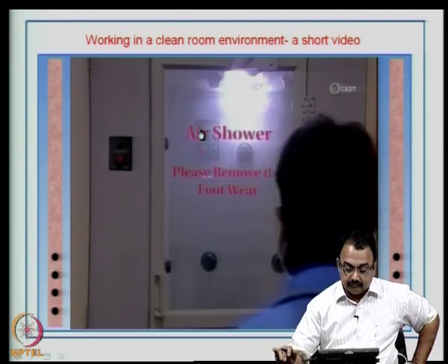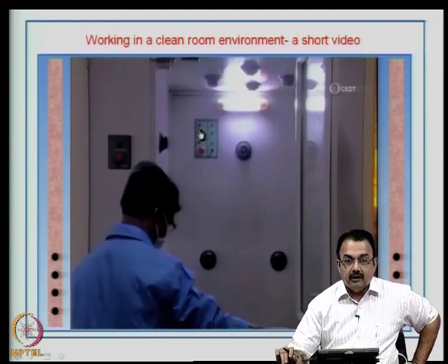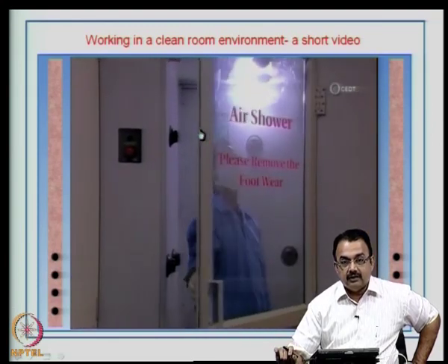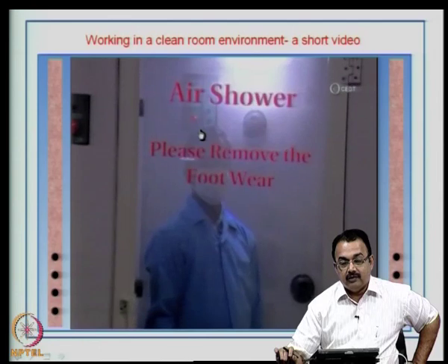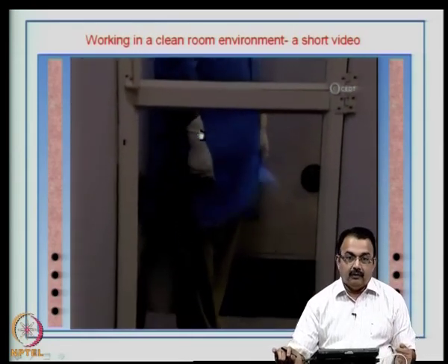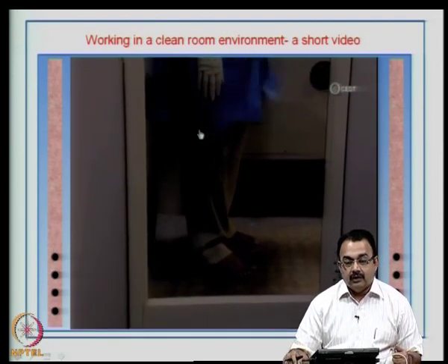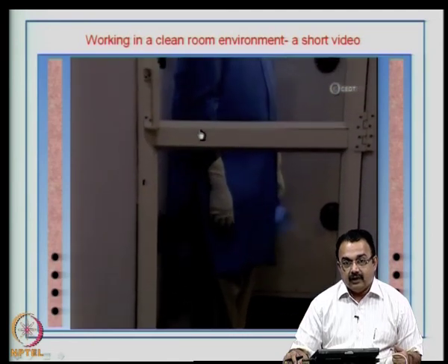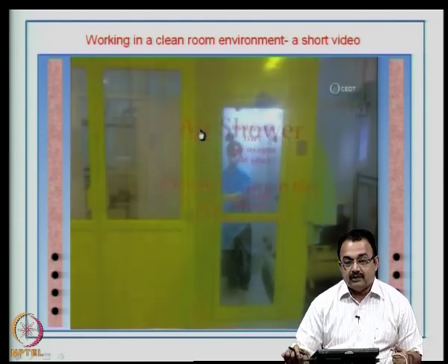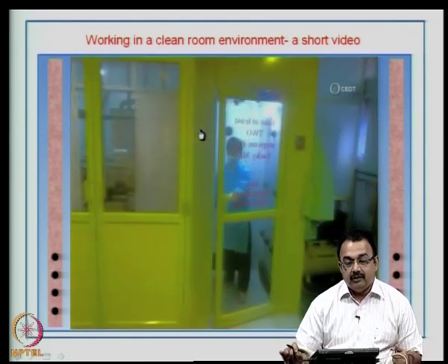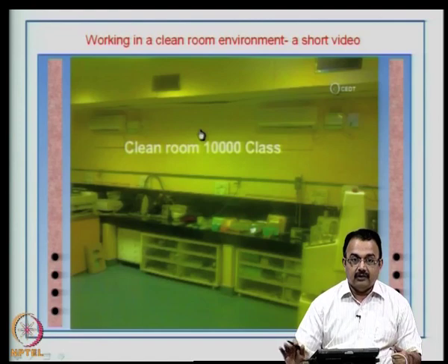Normally, in a lab or a manufacturing setup, there will be an air curtain and also an air shower. Any personnel entering the lab need to have an air shower. The air shower is used because it will blow away all the dust from you, from your hair, from your clothing and so on, and this will prevent all this dust from entering the lab. Because, as I said, a speck of dust falling on the surface of the PCB is going to get translated along with the design.